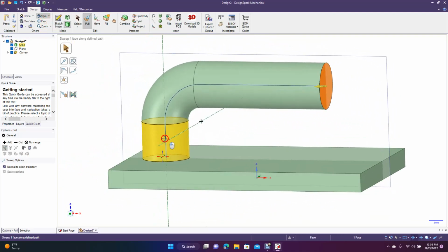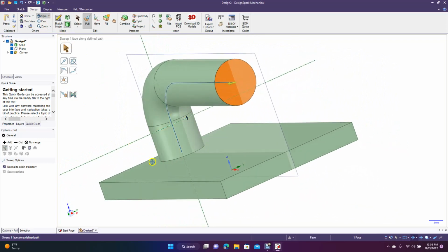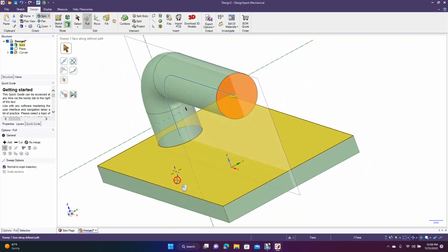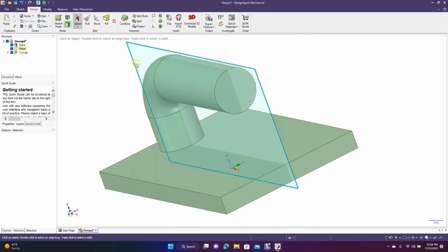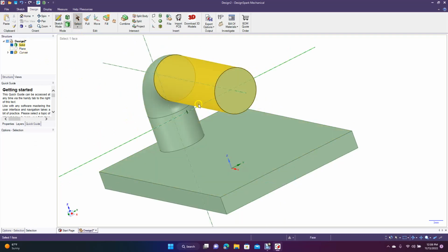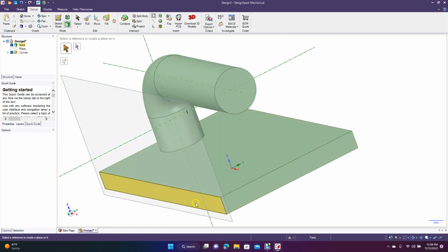Now if we wanted to put a shape here, maybe a shape coming out of here, we have to add another plane. As we move along, we can come over here and take the check off the plane so we don't get confused. So now we're going to have to add another one. We'll go to plane, and whenever you add one, you can either click on the face that you want to put the plane on, or you can come over here to the X, Y, Z coordinates.